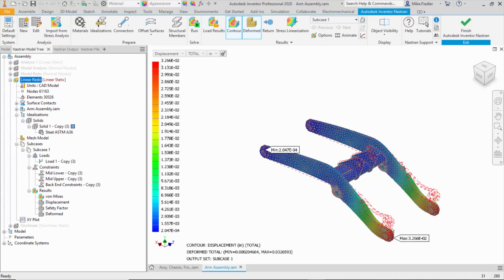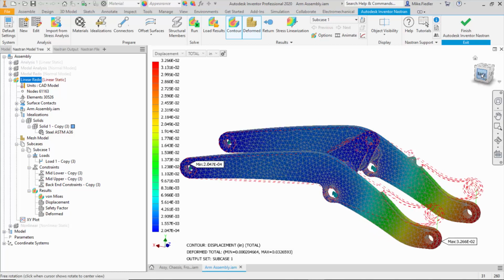And when I look at the displacements on the geometry, the other thing that I see is I have a gradient, right, going from a maximum displacement near where my loads are applied down to essentially zero displacement where my constraints are applied. So that looks good to me too. I don't see any one individual part which has some massive displacements on it, which would indicate also that it's not connected to the structure, if some component was able to just fly off in space. So that tells me that it's all connected together.